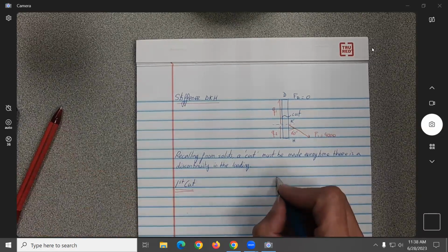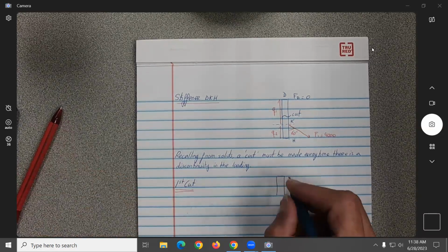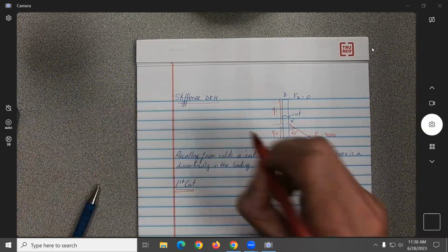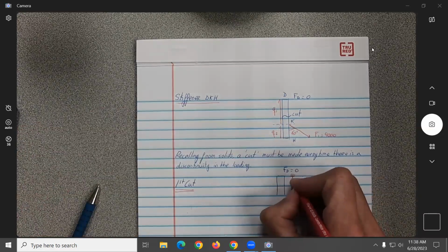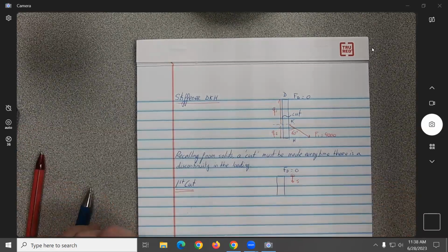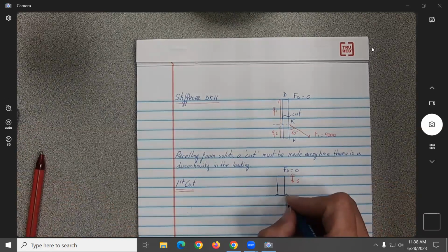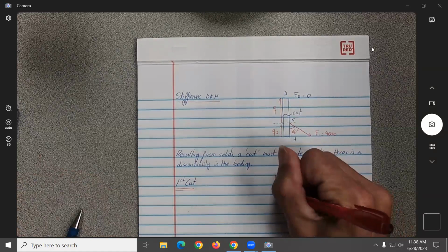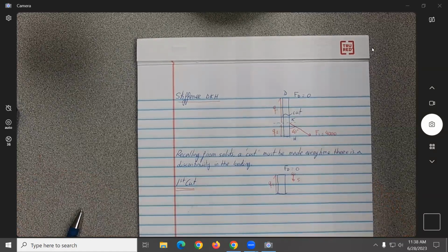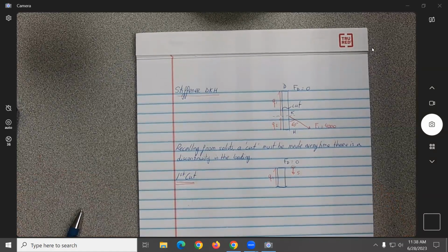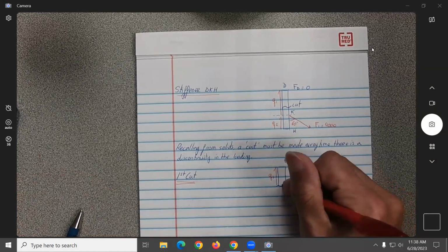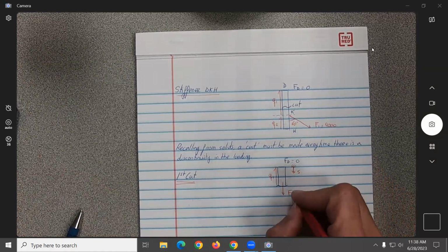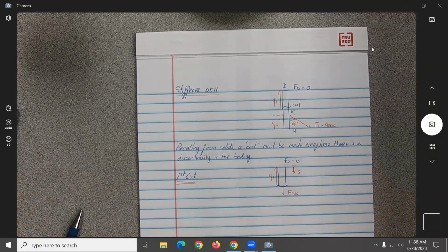So what do we need to do? We start from point D over here. We know F of D is equal to 0. We start over here the deformation. Let's say this will be S. Then we make the cut over here. So you will have only Q1 over here. And what I'm trying to look at is not the moment, but just the axial force, no? The force in the member. So let's call this one over here, I'm assuming tension, F DK. If you have any question about what we're doing, stop me, okay?